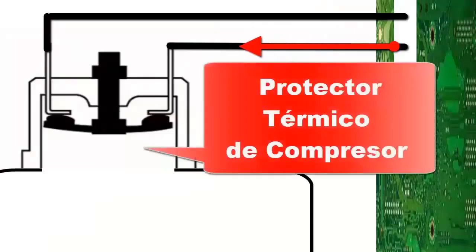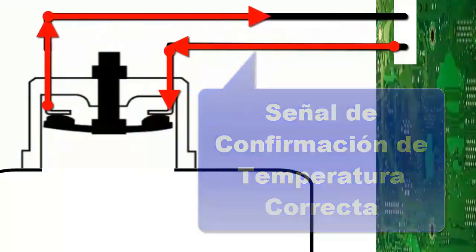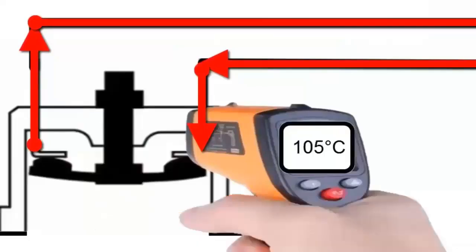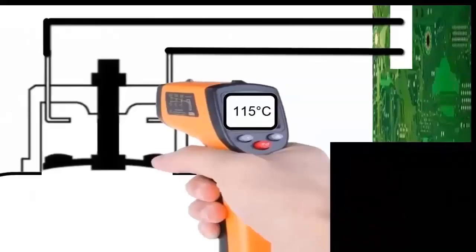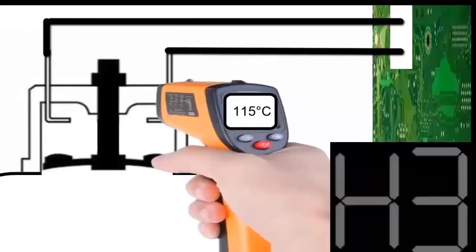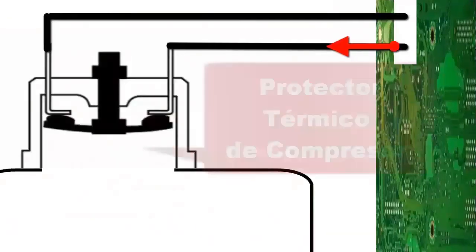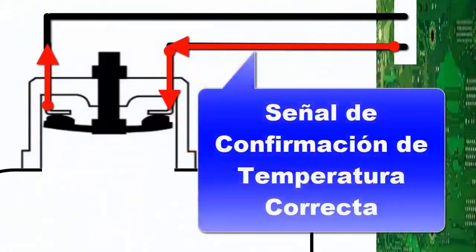F. Overload detector problems. In many compressors, there is a thermostat located on top of its housing. This thermostat receives a signal from the external electronic board. When the thermostat detects a temperature above normal, it interrupts the circuit signal, allowing the electronic board to identify the presence of high temperature. This triggers a fault code or activates a protection, which shuts down the equipment to prevent potential damage. Also, false alarms due to false contacts in the thermostat or problems in the thermostat itself should be ruled out.